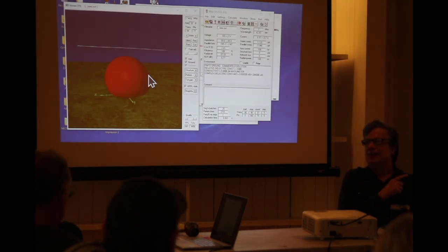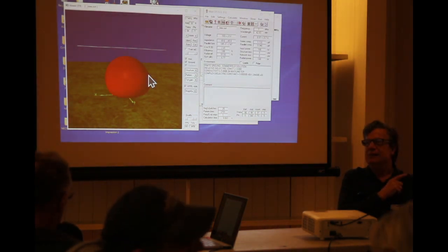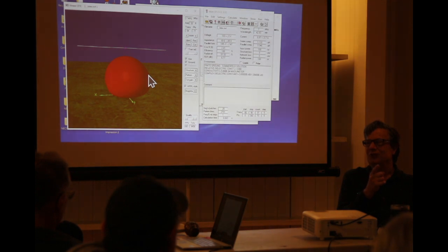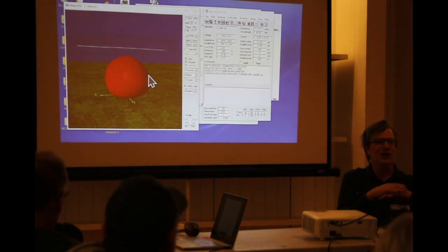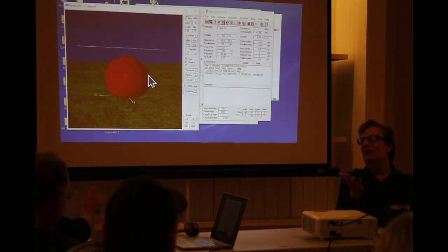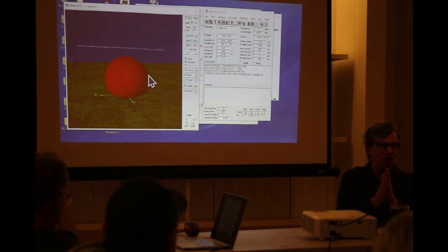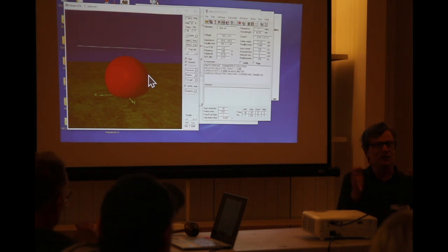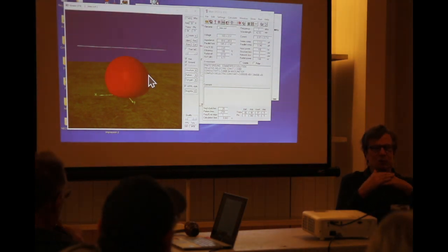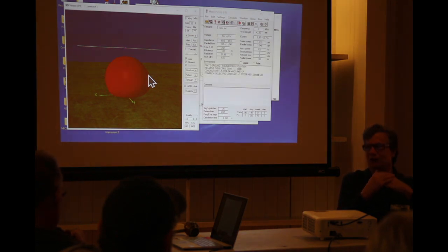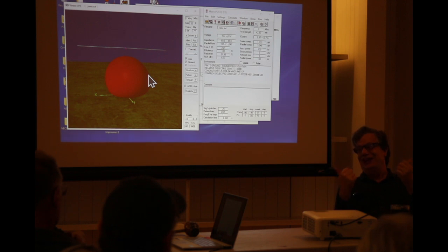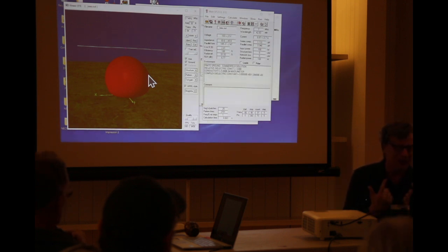It's going straight up. No, it's a DC resistance or skin effect resistance. Okay. If we had superconductivity, we could do that. But there's a diminishing point. It's about 1/8 of a wavelength where the losses of the ground system and your antenna start equaling the gain of the antenna. So somewhere between 1/8 and a quarter wave, we actually have, well, I should say for what we're doing at HIPAS down in Wyoming, we were trying to get maximum strength upward. We're using between an eighth and a quarter wave.